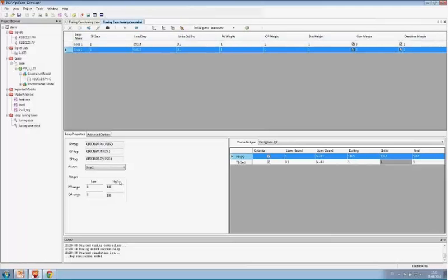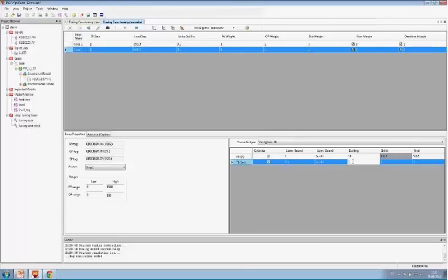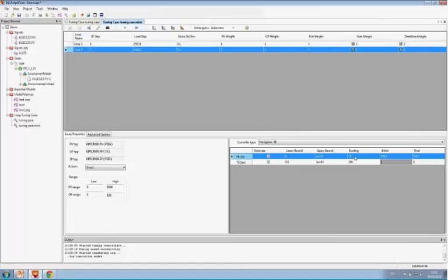Now for the second loop, my P-value range is 0 to 1500. I also have a PI control in PI mode, and I have 50 and 100 as existing tuning. So this is just the same as the last time, and I will run fine tune now.